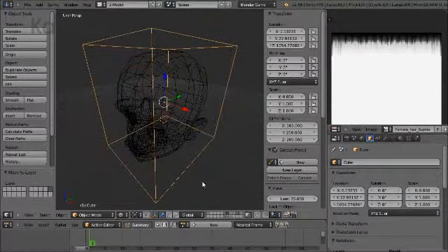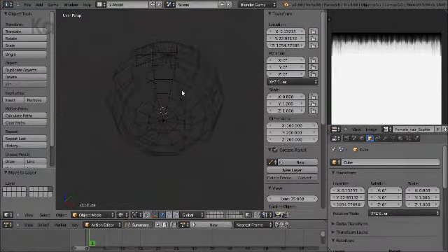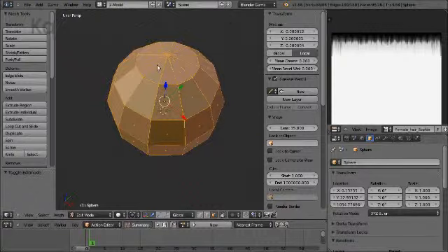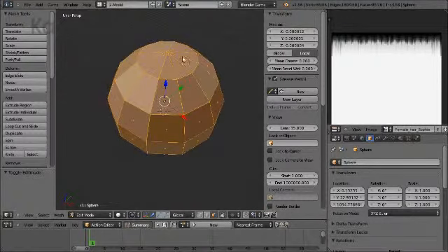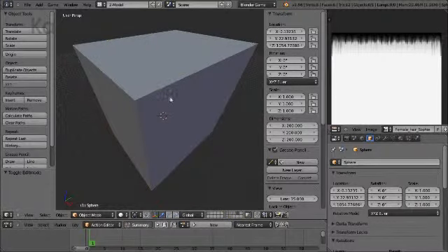Now, depending on the style of hair that's being made, it's often best to start the object from a cube as opposed to a sphere. This is primarily because of UV issues that are caused by the poles. That's this area at the top and the bottom of the sphere. These pole areas cause problems with UV maps. It also causes problems when editing the mesh because it's not as easy to do. We can show that by editing a cube that's already been added to the scene.